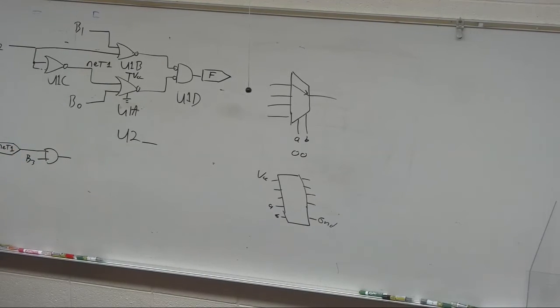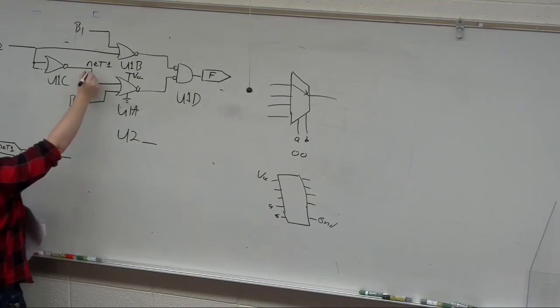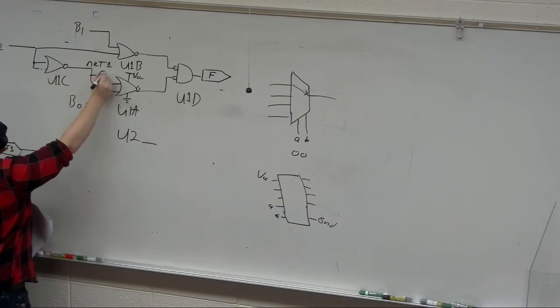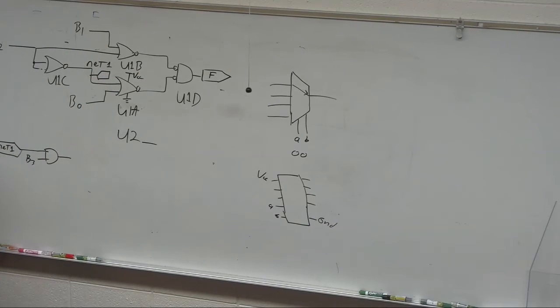So there's 2 different ways that you'll see it. If it is in the same schematic, so on the same paper, I don't need the port. I would just write net 1, right? And because this one is named net 1 and that one is named net 1, they are connected. If this was on a different sheet of paper, I would add a port there and a port here. And that would let the schematic know, or you, the person looking at the schematic more specifically, that you can expect to find this net somewhere else on a different sheet.